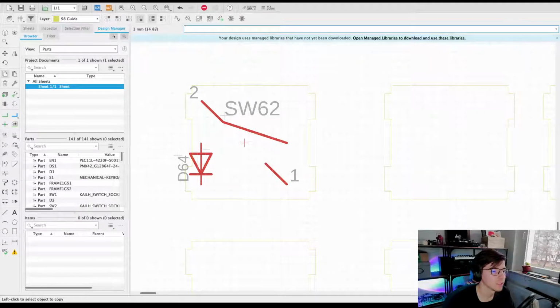Okay, for every switch we need a diode, just because it will be measured through your rows and columns. Your microcontroller asks whether these are connected or not connected. So from a big O perspective, you would go through all endpoints and ask whether this is connected with any of these: whether input 1, column 1, is connected with row 1, row 2, row 3, and so on. And you just go over this over and over multiple times per second. And this is the way it works.